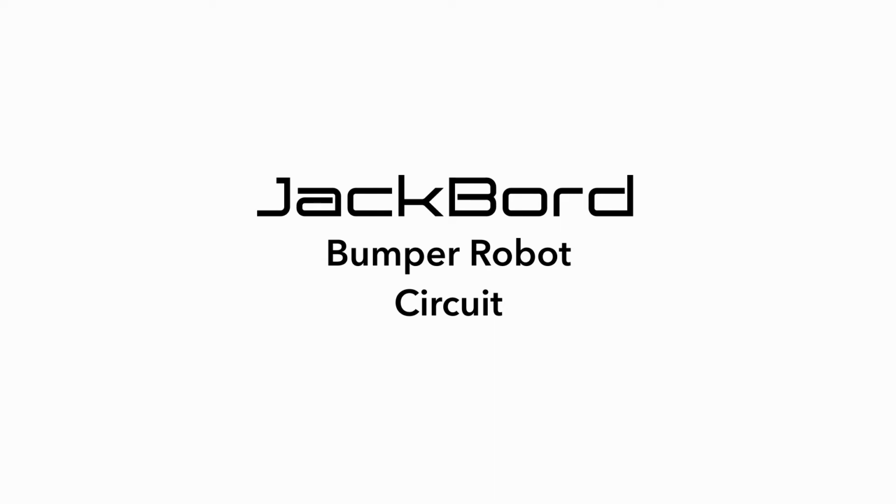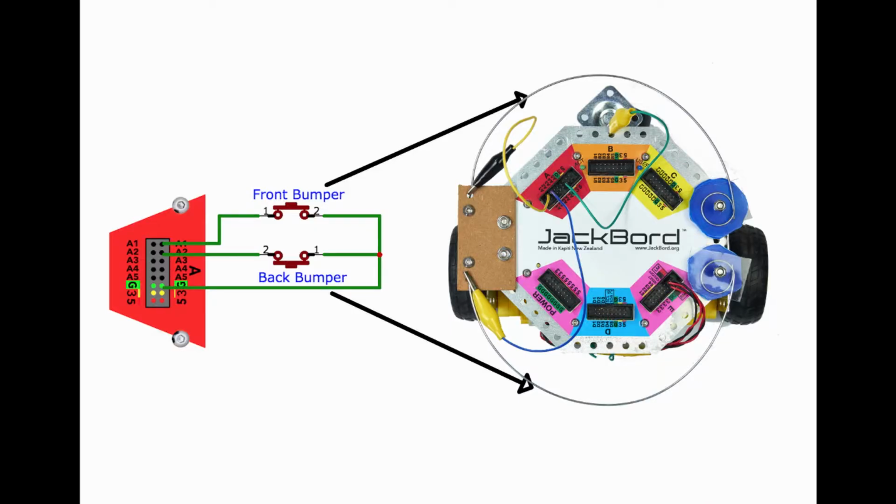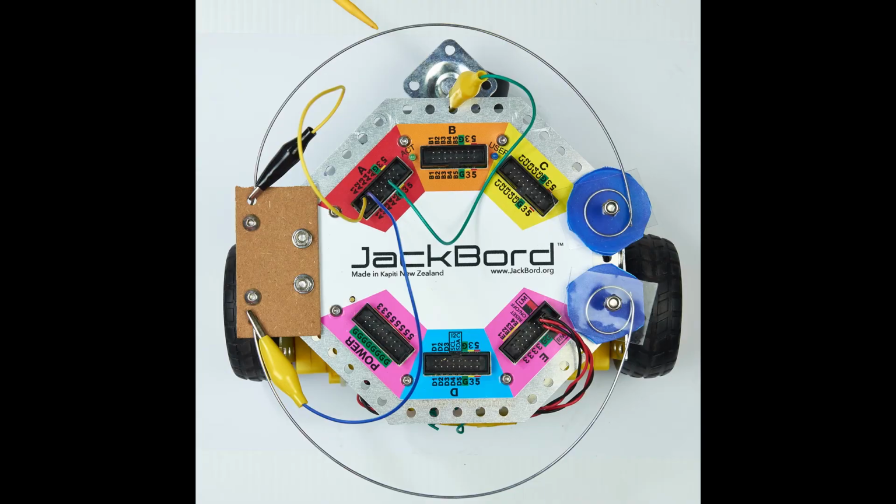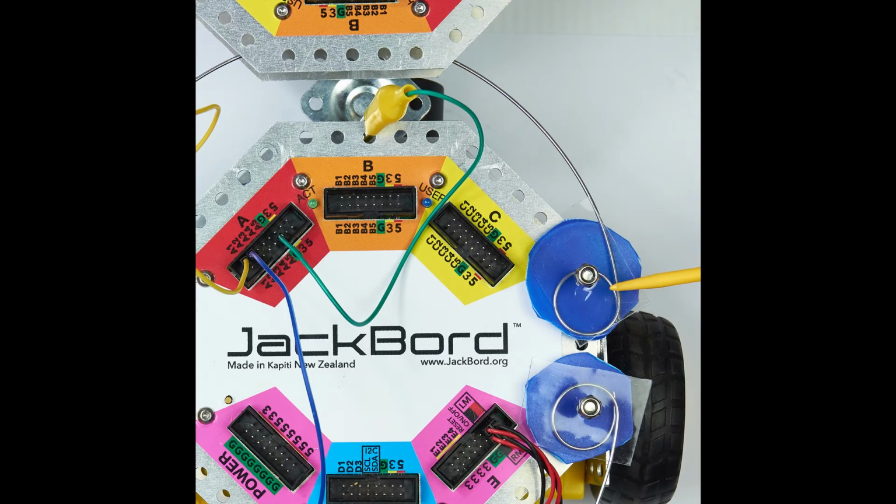Bumper robot circuit. Before we get into the code, it will be helpful to look at the circuit diagram of the bumper robot. The first thing to remember is that basically we're dealing with two switches. The first switch, which is connected to port A1, is on the front bumper. So when the robot bumps into something on the front, this switch is closed.